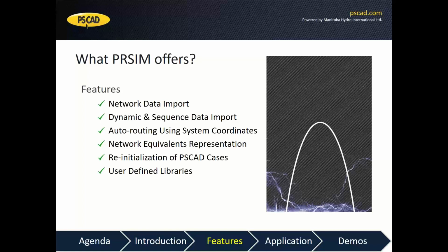And it also re-initializes the generated PSCAD projects to save your time and effort, because we are aware that once you build a PSCAD case through PRSIM, you might take it to PSCAD and do lots of different tweaks and modifications, like adding control signals, monitoring signals, and all those kinds of extra pieces of information.